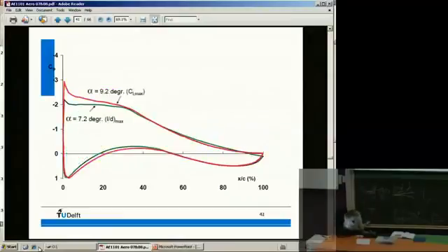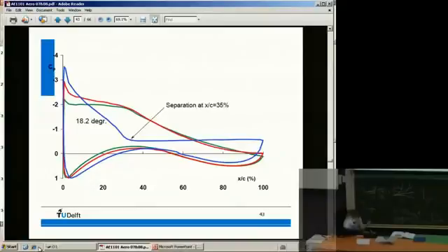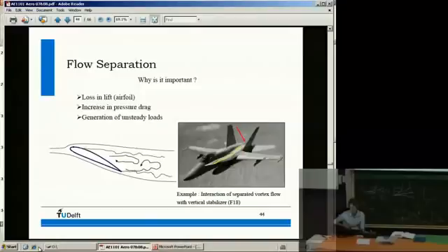And if you continue, 18.2, so very high angle of attack, you get the separation point here. So the separation point moves upwards. And it can happen really quickly. For example, it can start as a small bubble, but after a certain angle of attack, it just springs open and moves to a leading edge separation. That's why it's such a non-linear behavior. So in the next chapter, chapter 5, airfoils and wings, we see what it really does to your lift and airfoil.